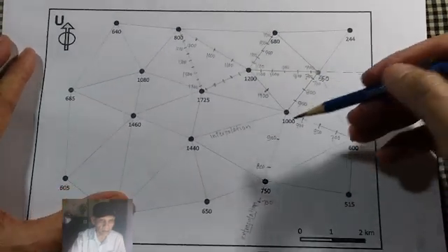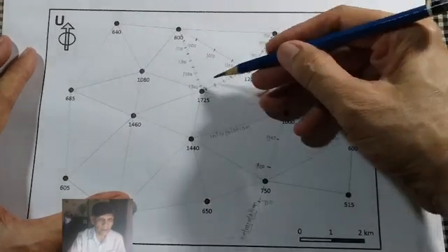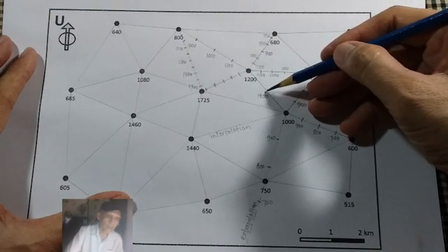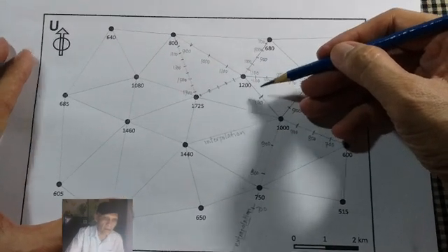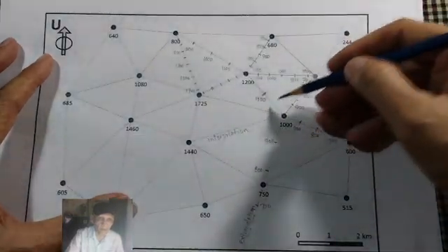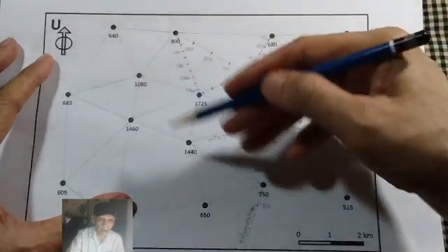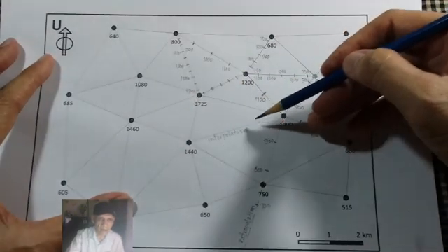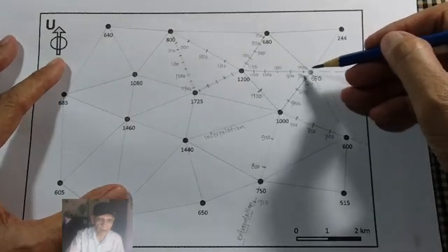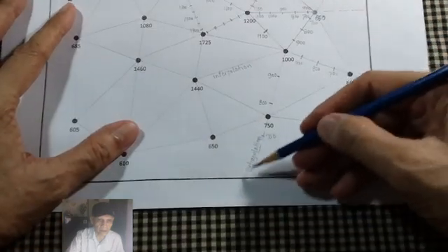The next step is dividing the distance according to the contour interval which we will apply to this map. A connection between two points inside the picture is called interpolation. But if we want to add points outside, we often call it extrapolation.